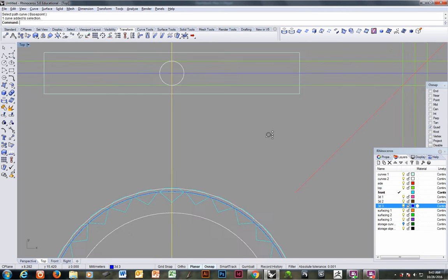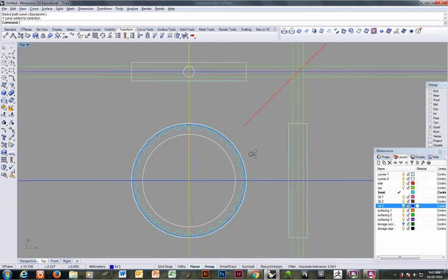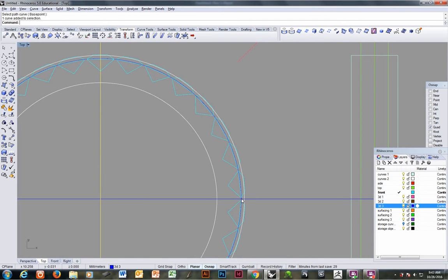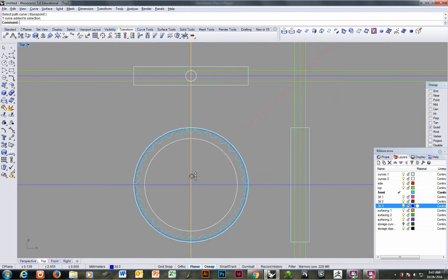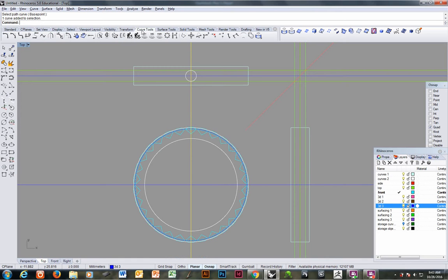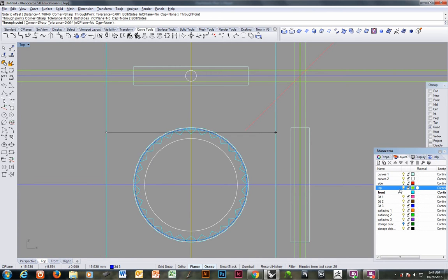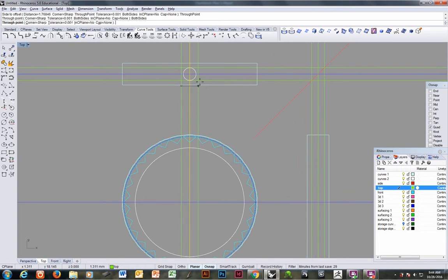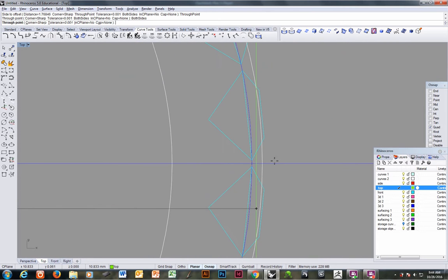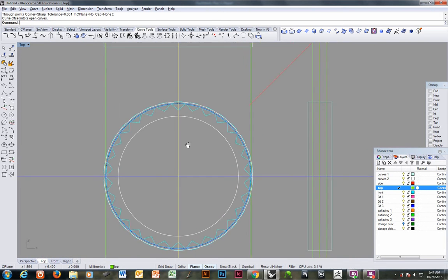First thing we need to do is to chart the width of this channel that we have made to set our stones in. So offset, through point both sides, construction line layer. Going to grab this quadrant or intersection, either one is fine. They're the same position, same location.